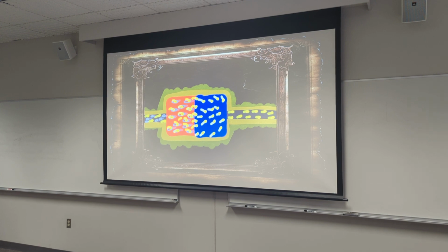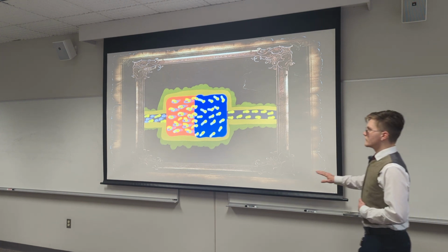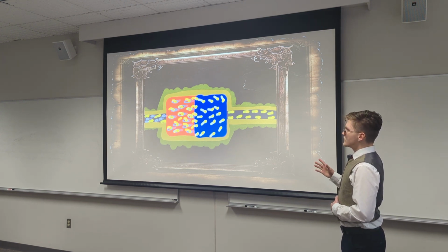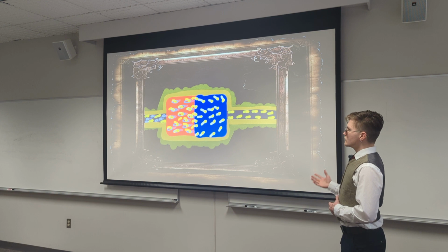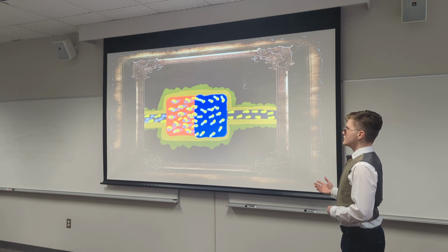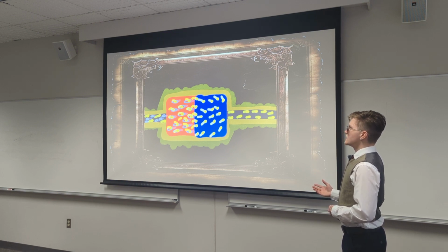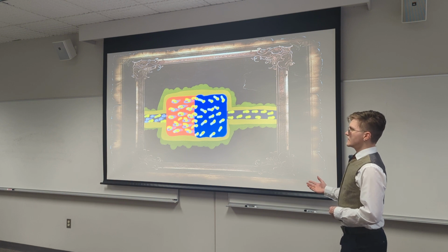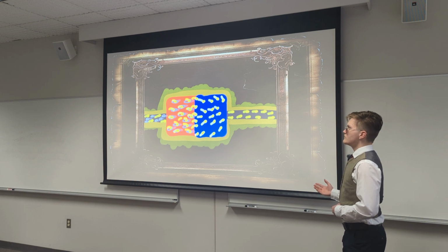As I said, it's just like LEDs, but in reverse. You can actually use LEDs as a photodiode, but they're not very efficient. And you can use photodiodes as LEDs, but they're also not very efficient. So the difference between the two is that photodiodes are optimized to absorb light, and LEDs are optimized to emit light.